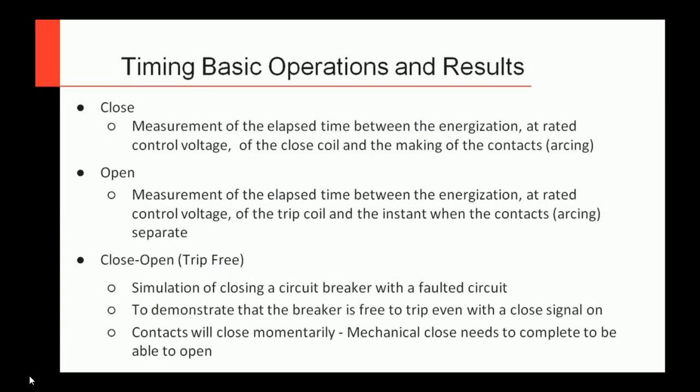So, timing, basic operations and results. What are we trying to measure here? We know where everything should be hooked up, but now we actually want to get some measurements. The first thing, of course, is close. You usually get to your circuit breaker and it's open, so you go ahead and close it, and this is really just mimicking putting the circuit breaker into service.